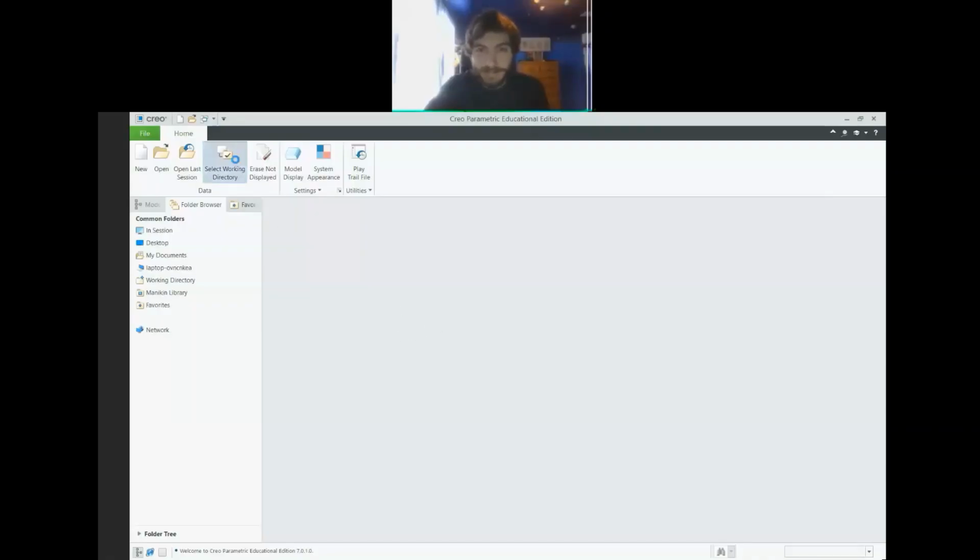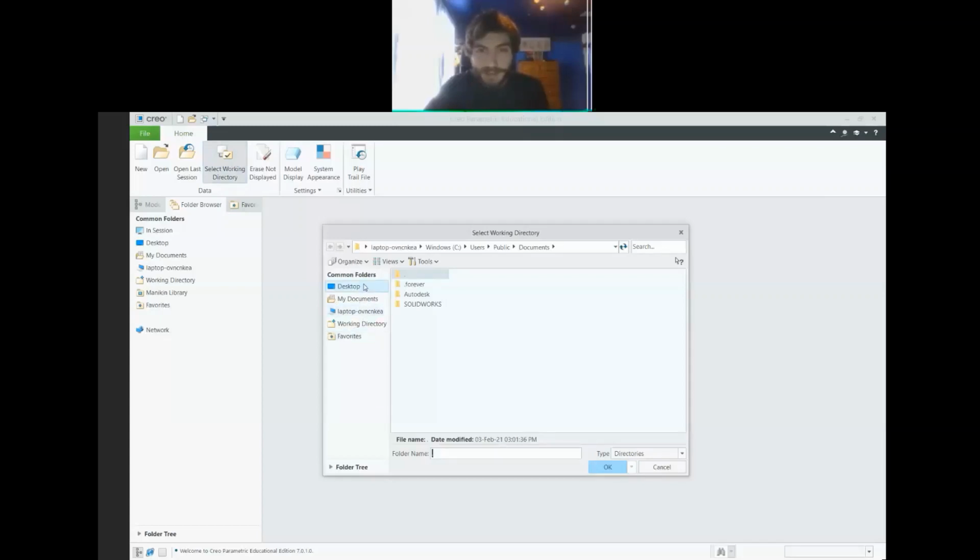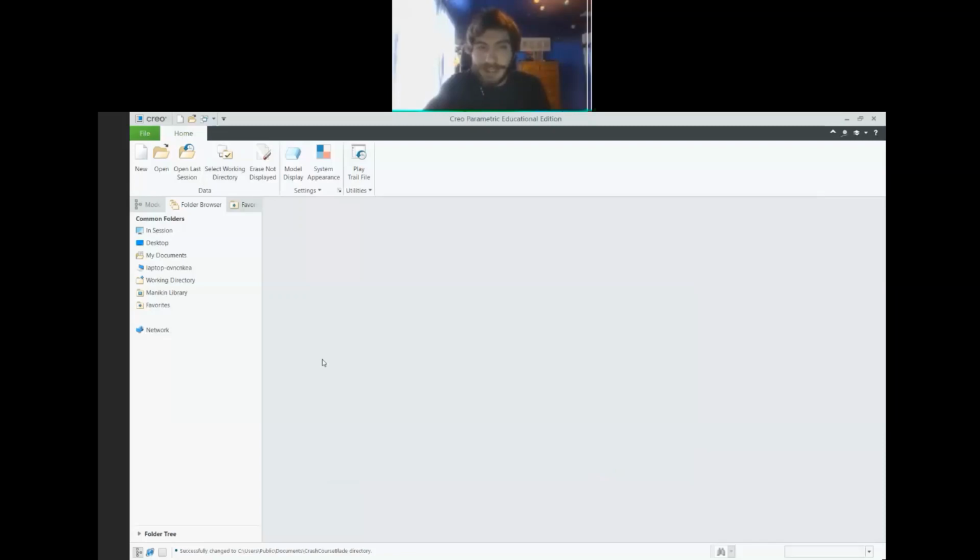So we're going to go ahead and select our working directory. Documents is fine. I'll create a new folder. We'll just call it Crash Course Blade. And so once you pick whatever folder you want, you press OK. And this is where all of the things we do for the entire time we have Creo open are going to be saved by default. If you don't do that, you won't be able to get past versions of your file.